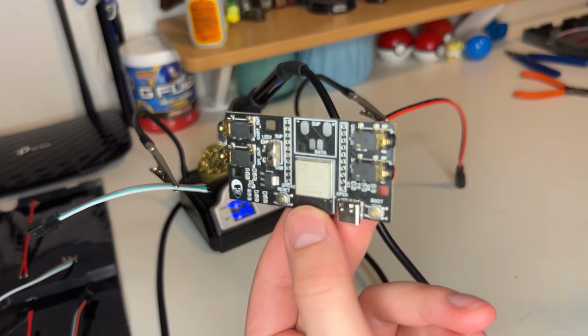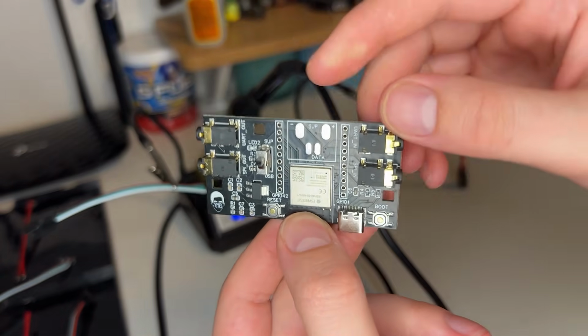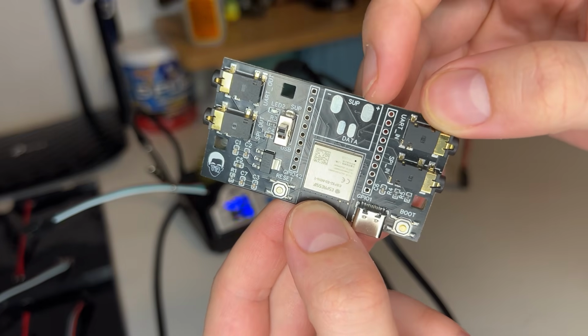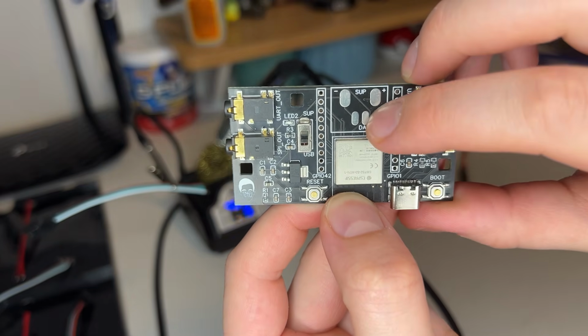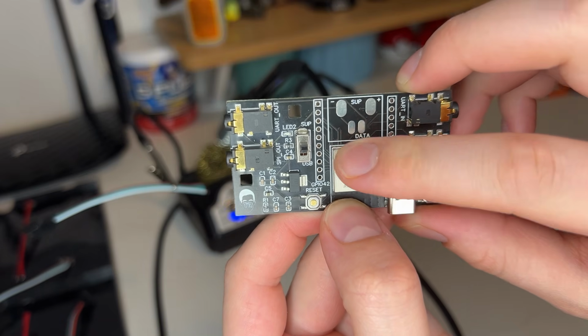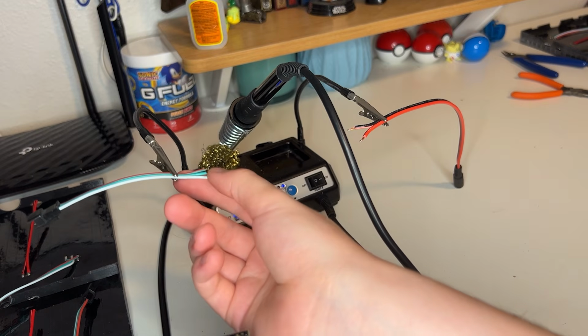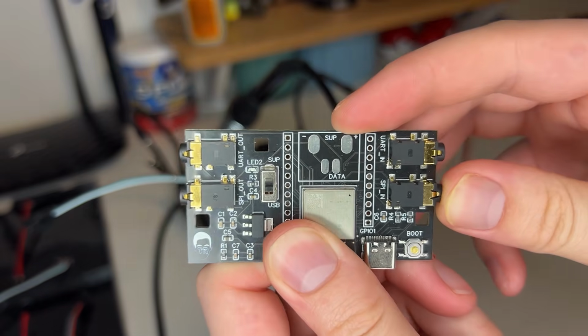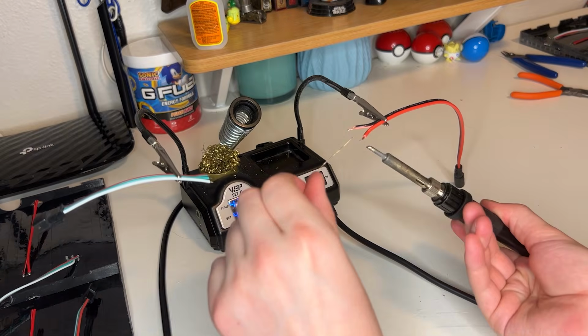All right, this is pretty straightforward. On my little board here, I have supply power up here, minus and plus. Black goes to minus, red goes to plus. Down here, I have the data pin. This pin next to it is the negative terminal for our connector here, which is this white cable. And then the red one is also gonna go to this plus. So let's do that real quick.